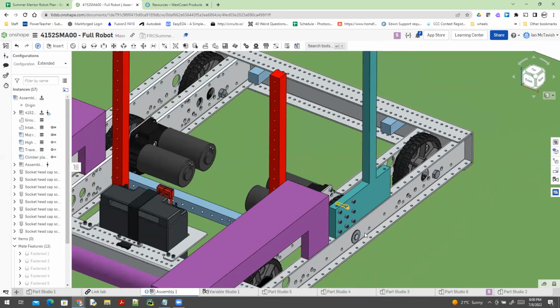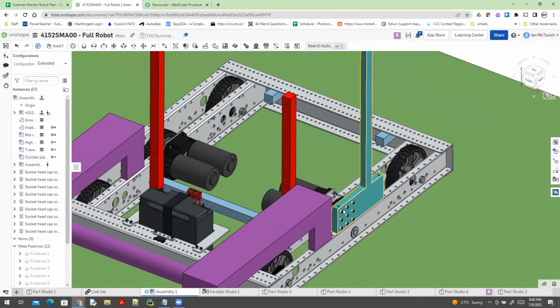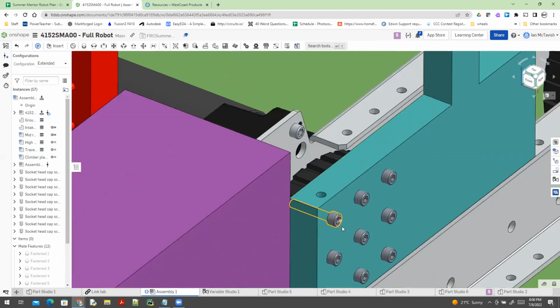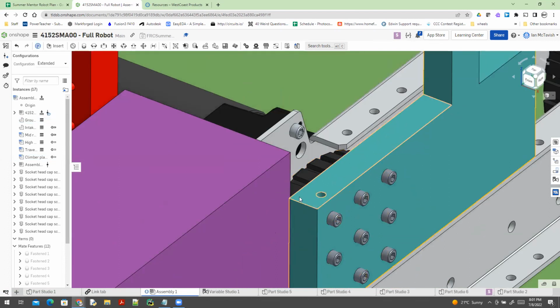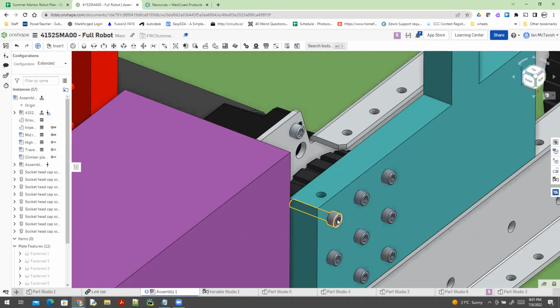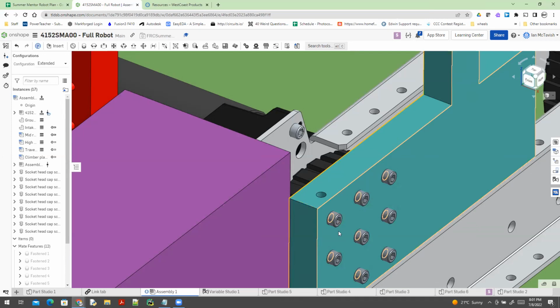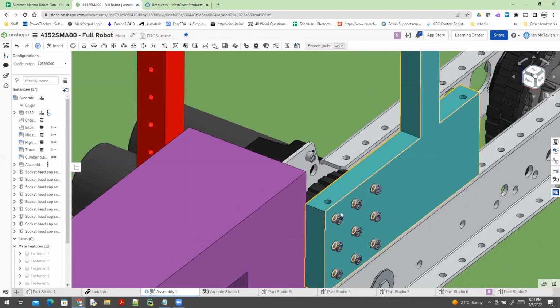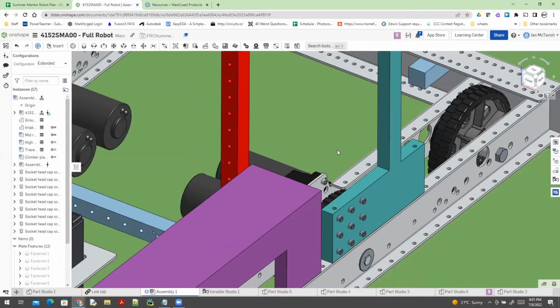makes it easy. But when you're doing it, you want to really think about, okay, let's say I'm screwing this in. Well, where does my tool go? So maybe it's easier to put the socket on the inside because my Allen key I can fit in there, and I can use a ratchet on the outside to be able to quickly remove the item. So it's about thinking of those things and then designing using that kind of strategy.